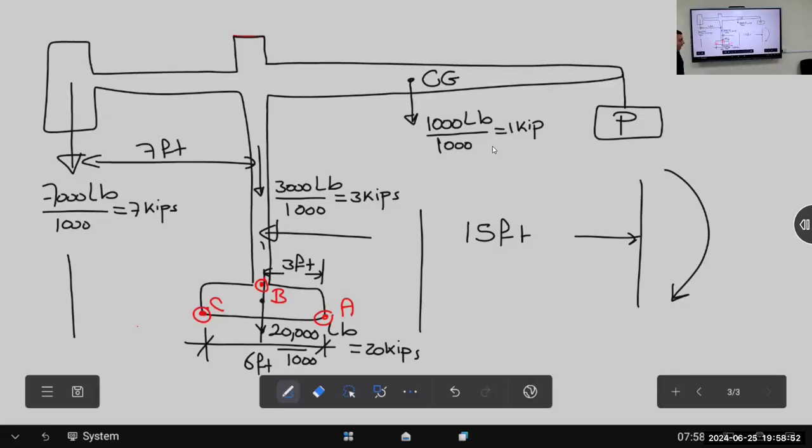Now I will take a line here. Now I have forces in the right hand. Where are the forces in the right hand? The 1 kip load. So what about the left hand? The weight of the post, the weight of the foundation, and the weight of the counterweight. All this load will give me moment. It should be moment under equilibrium. If this load is more than this value, sure, 100% overturning will happen.